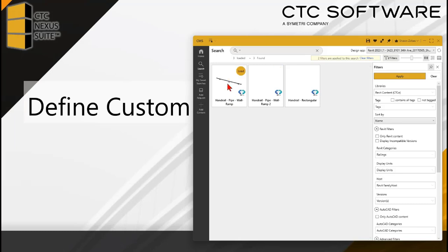Sometimes this one here looks good. There's a reason for that. Normally railings show up like this. They have no preview. When we were over there in our preview settings, all of the Revit categories that were listed there were for family categories that are RFAs, Revit families, that can be saved out of a project.